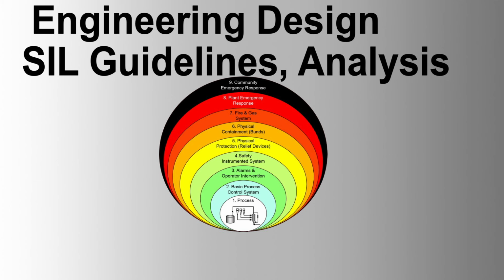The FTA process for SIS involves several key steps. 1. SIS description and application information. Gather detailed information about the SIS architecture, instrumentation, process description, support systems, testing frequency, failure modes, diagnostic coverage, repair intervals, maintenance procedures, common cause failures, and systematic failures.